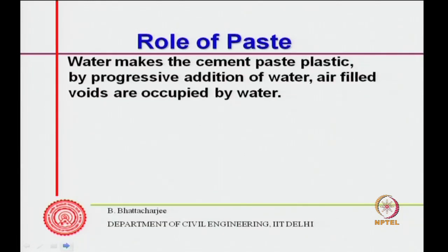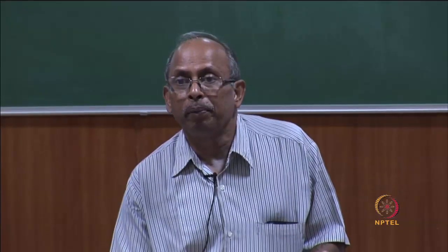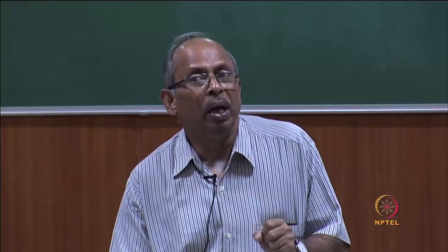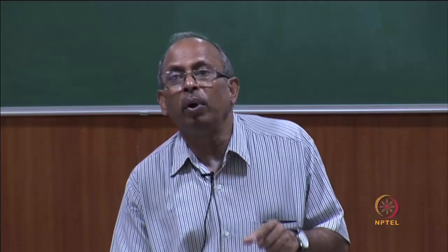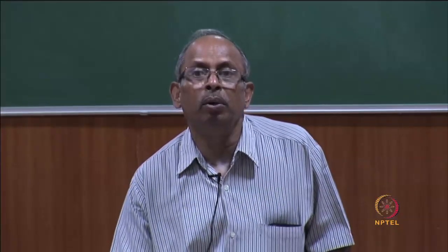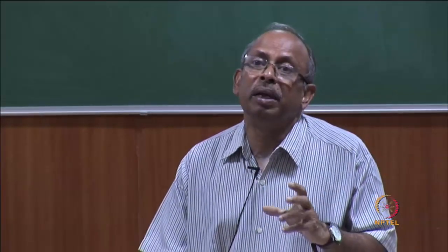Water makes the cement paste plastic. By progressive addition of water, air filled voids are occupied by water, and if you recall, I talked about basic water content sometime, which is achieved when all open air voids are isolated by water, right. So, all air bubbles get isolated within the interstitial space of cement system. Water coats all the cement. So, all open air voids are isolated by water, and this corresponding consistency we call normal consistency. So, therefore, water in the paste is very important.